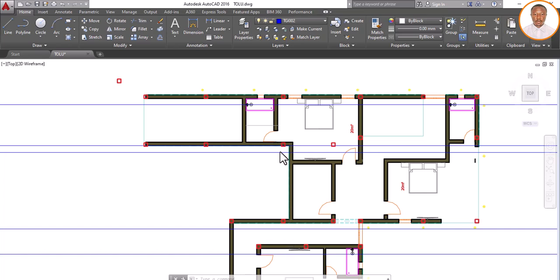But in a case like this, what you do is design based on how it is, so that when they get to site, they shift this one backward. It will not be good to do it like this, because what's going to happen when it's raining? When it's raining, what will happen to this slab? You cannot go and tell your client to roof this place separately. When it comes to access, it's not actually okay, and you are going to increase the cost for your client of roofing this particular place.